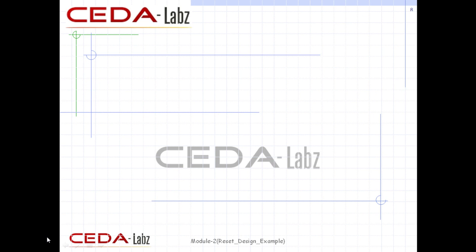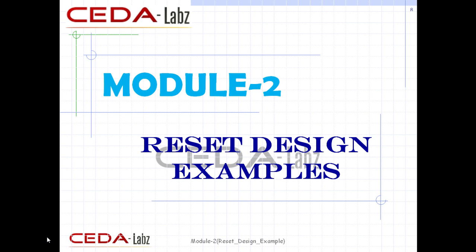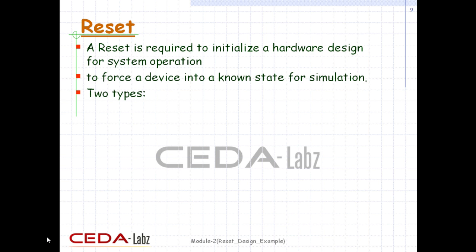In this tutorial we will study about reset, and we'll see some examples of combinational and sequential logic implying the same. A reset is required to initialize a hardware design for system operation and to force a device into a known state for simulation. A reset simply changes the state of the device or design or ASIC to a user or designer-defined state. There are two types of reset. What are they? As you can guess, they are synchronous reset and asynchronous reset.